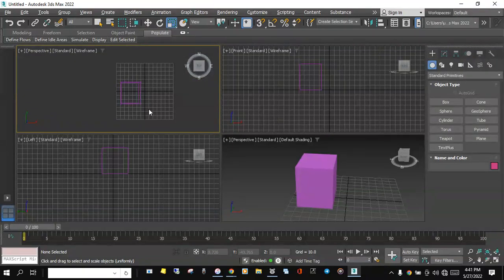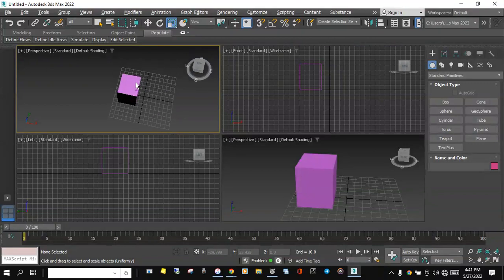But if you can see now, everywhere around here is showing wireframes. If you like to change it to the default view, fine. Currently, it's showing as perspective view here, but showing as the top here. All you need to do is, like I said, use the Alt button and middle mouse button to orbit around an object. Here also you can control from different edges, very easy to use.